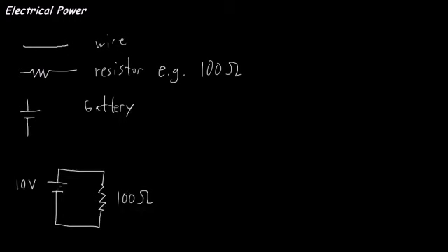If the voltage being supplied by the battery is 10 volts, it means it's 10 volts from here to here. You always compare the voltage of something by using 2 points. So you can't just say, what is the voltage at this point? That really doesn't have meaning. What matters is, what is the voltage between these 2 points? That's equal to 10 volts.